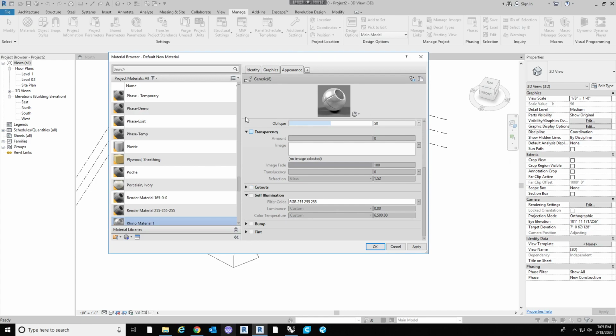So the other thing that you can do with materials within modeling software are bitmaps. What bitmaps are is a little bit different from a material texture, where it reads like black and white essentially, a grayscale, and you can have it do different transformations of a material based on the black and white pattern of the bitmap that you are importing.